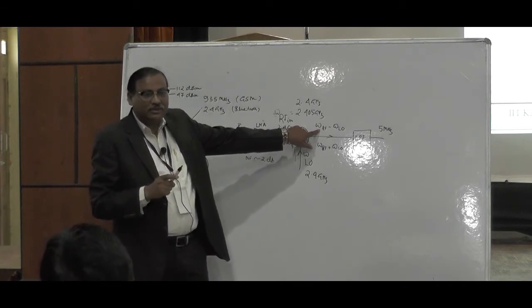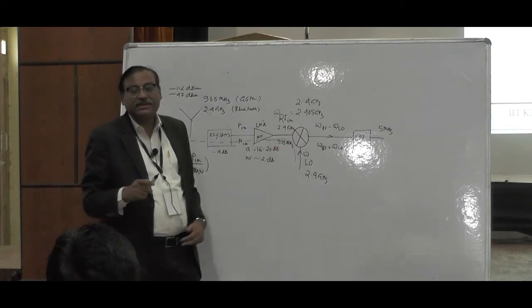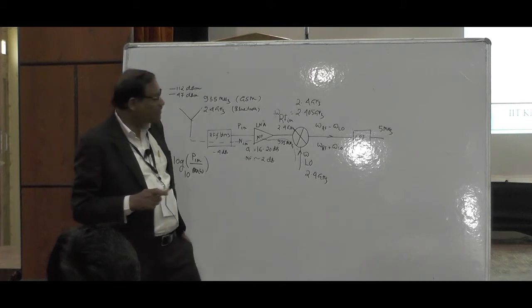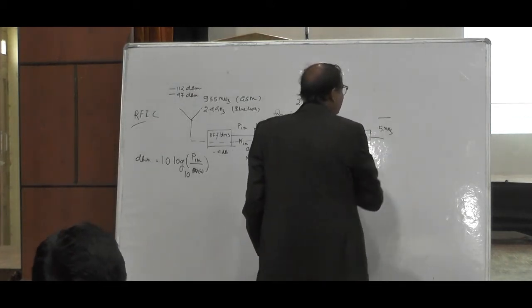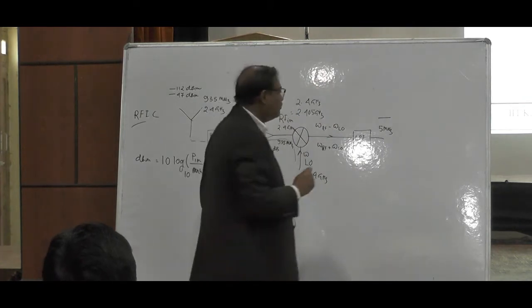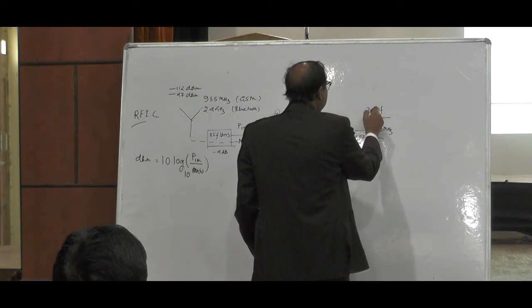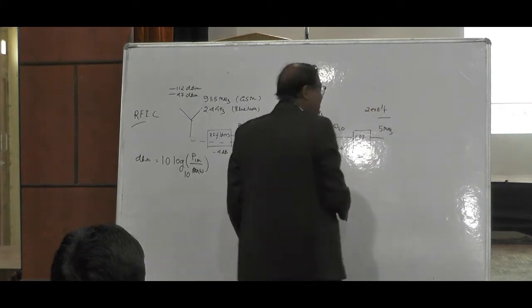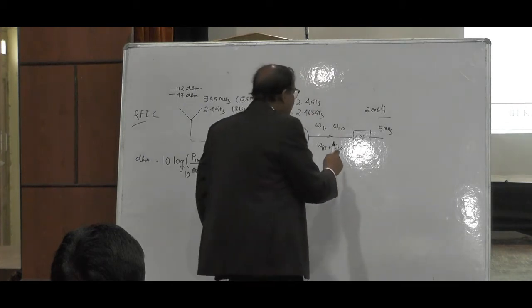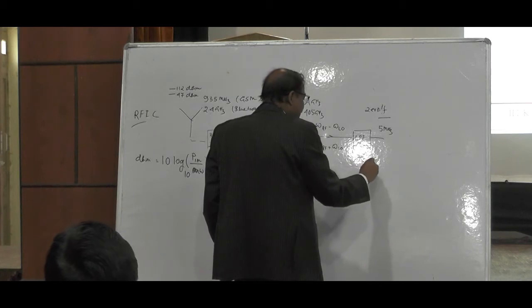So then A sin omega LO minus omega RF, that means it is a DC component. So in spite of 5 megahertz, you are getting a DC level, zero frequency. If that zero frequency signal comes, then consider an RC filter, I am giving a simple approach.